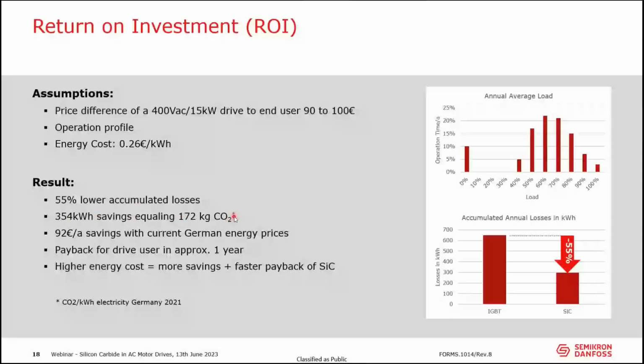So for that, I use these energy costs. Now you will laugh at me and say, hey, I paid this last time in 2021. That's correct. Now it's much higher, but it's also going down again. Anyway, if I do the calculation with these low energy costs here, then I would save in a year 92 euro. If you compare that to the price adder here, it's obvious that the added price of the drive comes back within a year. So now the drives typically are not designed for 1 year operation time, rather for 10 or